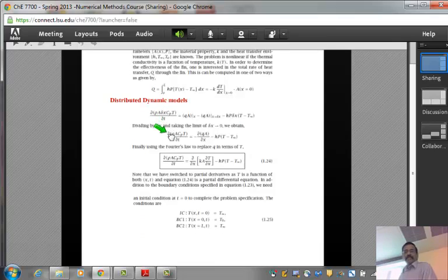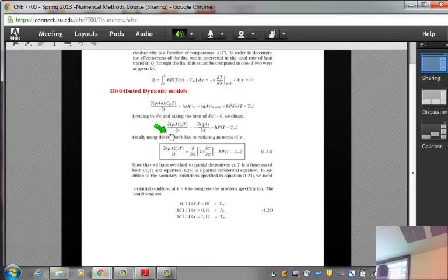And the last example is the same problem, but now I have a transient situation. This is a case where I'm just starting up the engine, it is heating up, so the base temperature is changing with time. Then questions like how long does it take for it to reach a steady state can be answered by solving this equation. The right hand side of this equation is exactly the same as before, and the left hand side is your accumulation term.